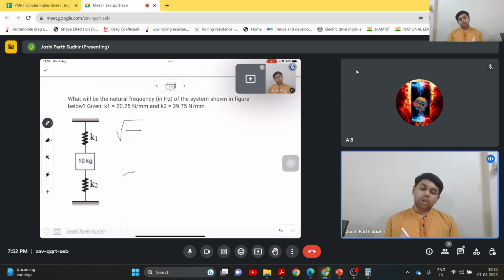If we are able to reduce it to a single mass and single spring, then the equivalent stiffness divided by the total net mass present in the system will be the natural frequency. So our job is to find the equivalent stiffness present in this system.